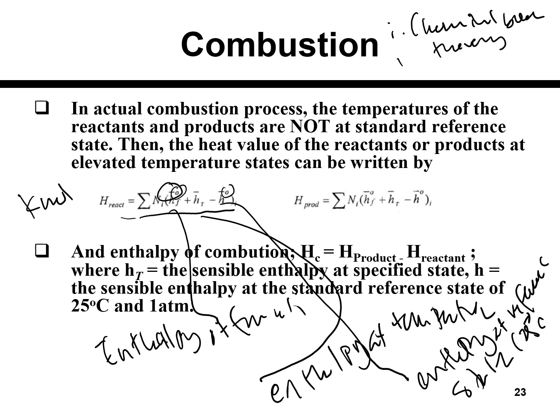Theory and actual. And then you calculate the air to fuel ratio, and number 3, you calculate the energy. You have to calculate the energy for each component of the substance, for example oxygen, nitrogen, and as well the fuel, for both the reactant and the product.